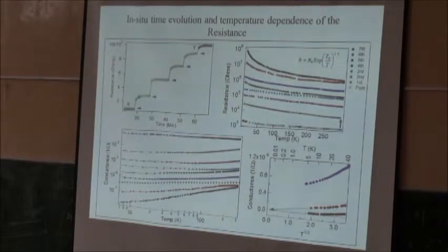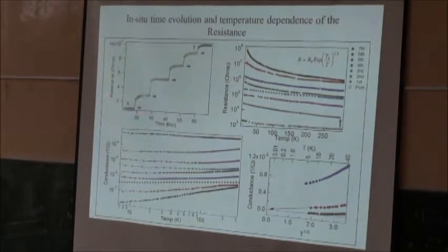Okay, let me see what happens here. Initially my sample resistance is about 1000 ohms. Then I turn on the plasma for a few seconds, then I turn it off. When I look at the resistance, you can see the resistance is increasing and it saturates here, going to almost 2000. After some time I again turn it on for a few seconds, then turn it off. Then we can see again it goes here. So I can stop any way I want.